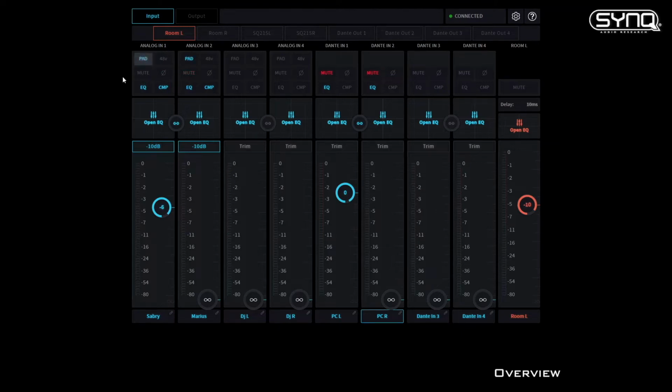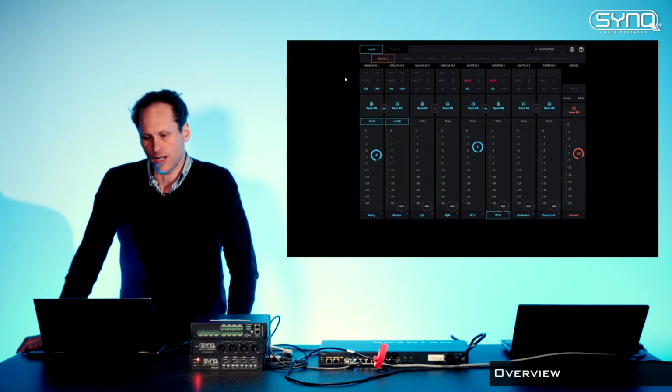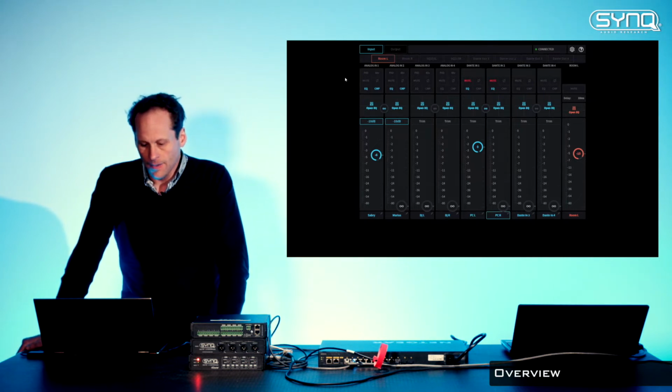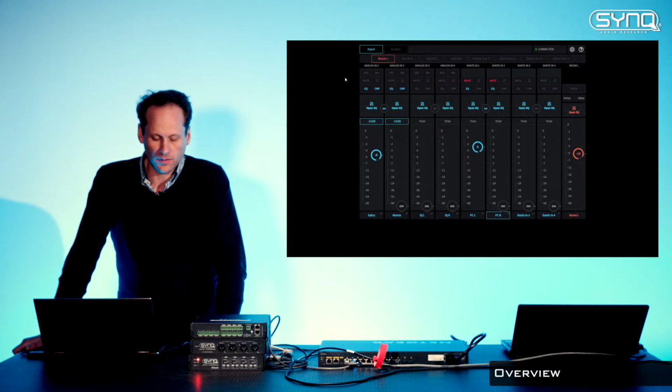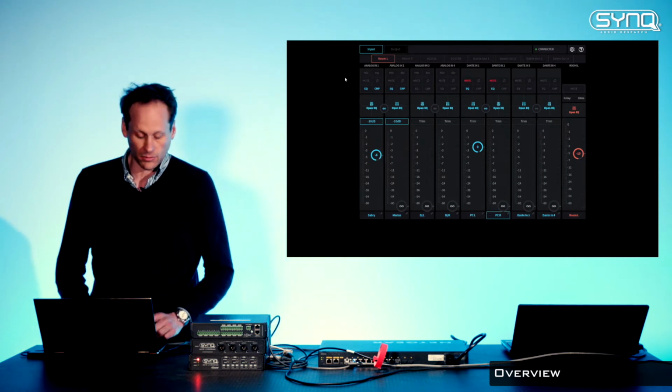If you click the pad, the input will be in line level. If you remove it, you will get the mic preamp. So we have the 48 volt phantom power. This is separate. For instance, if you have 2 microphones, one is a condenser microphone, the other one is a regular one, you need to set those parameters independently. So it's really depending on what you're going to do, but you could do it or you don't. It's really up to you.